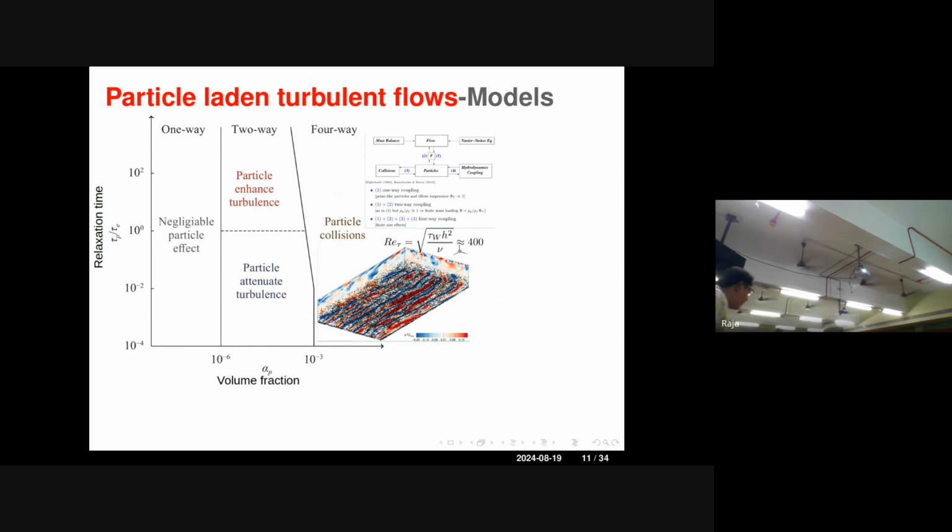There is some turbulent fluctuation, but if your particle has tiny inertia, it will immediately be struck by this flow fluctuation. Or do they possess huge inertia, where the flow pushes them, but the particle resists the flow and modulates the turbulent fluctuation locally, but after a while it starts moving because of inertia. So it's a really crazy way in which these particles modulate the turbulence of the system.